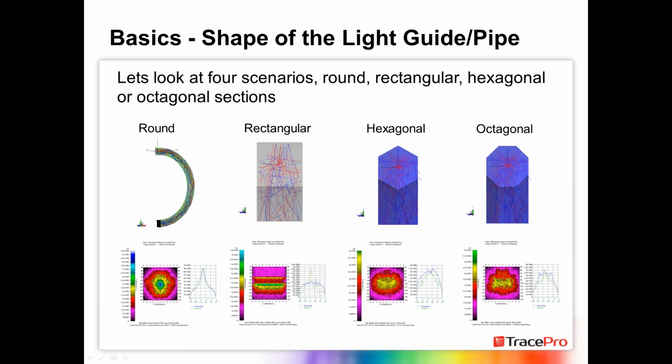So it's a system by system type evaluation. And you can go back and use TracePro to model the 3D printing by saying that the outside surface has a surface texture. If you've measured it and apply it to the surface, you should have a very close correlation between the two. Just change it from a perfect surface finish to whatever you're actually getting with your 3D printing operation.